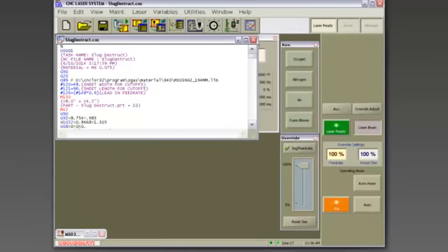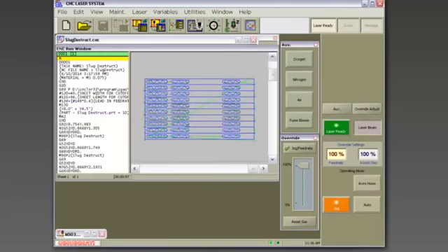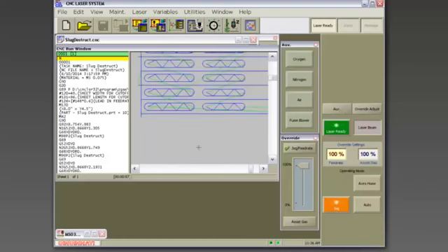So our final nest is the Slug Destruct, and this is the one where we worked with SigmaNEST to develop this technique. In a production environment, when you're doing slots and you don't have the ability to tab them, you do what's called a Slug Destruct. Well, typical programming softwares, they either want to do a Slug Destruct in the horizontal or the vertical direction. And by doing that, you are putting kerf cuts in there, and it adds processing time.